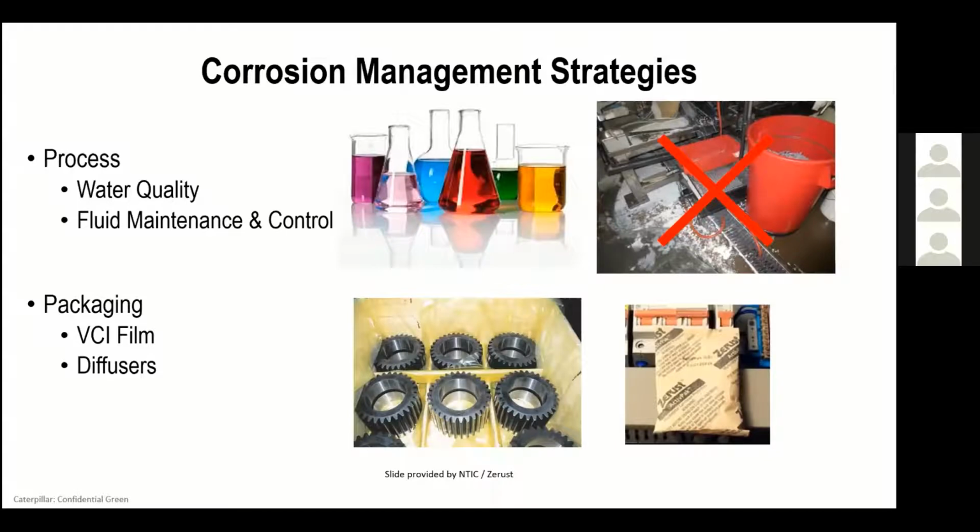Now, eventually, when you do that, you can take a look at this image down below, and you'll see kind of a yellow film that's in a bag. As we mentioned, you want to make sure that part is dry and packaged, because as we know, moisture really provides that environment for corrosion on that metal surface.